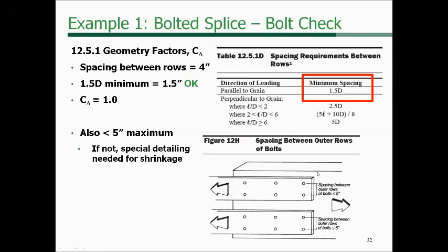So as this wood member, even if we come in at less than 19%, which we said we are in this particular case, we're going to dry down to an equilibrium moisture content of somewhere around 10%. And so the rule of thumb is that for every 4% change in moisture content, you're going to get a 1% change in the dimension of this wood member.